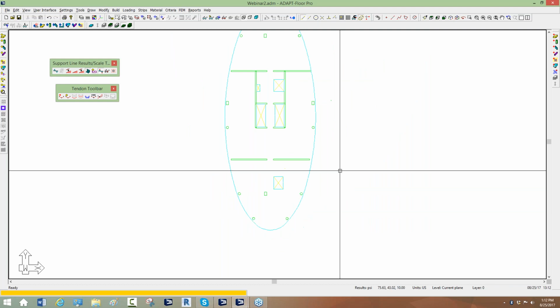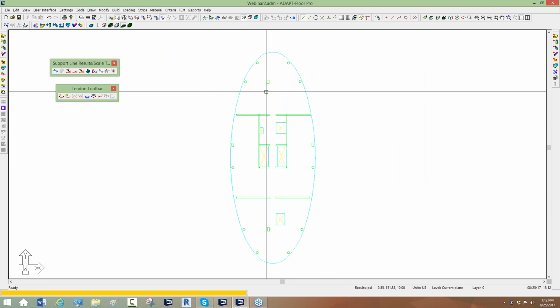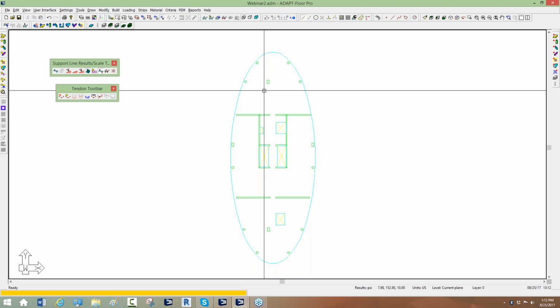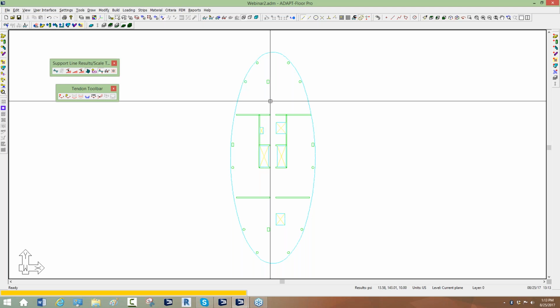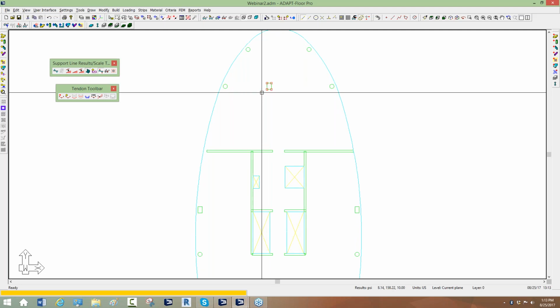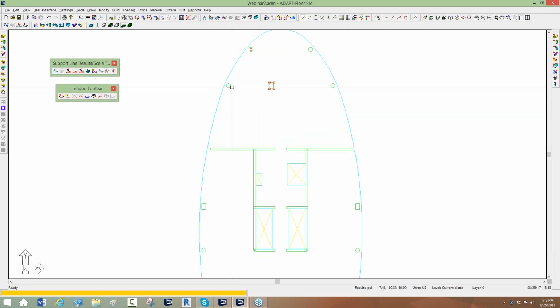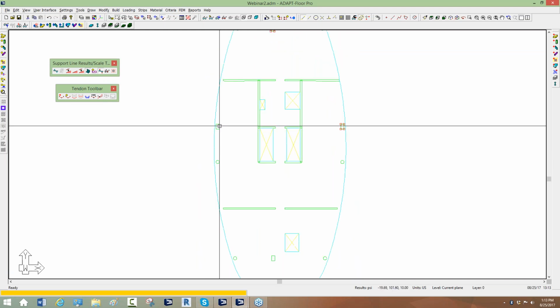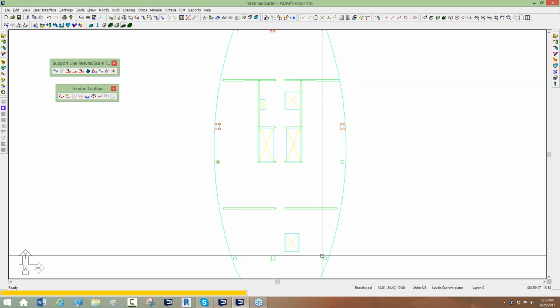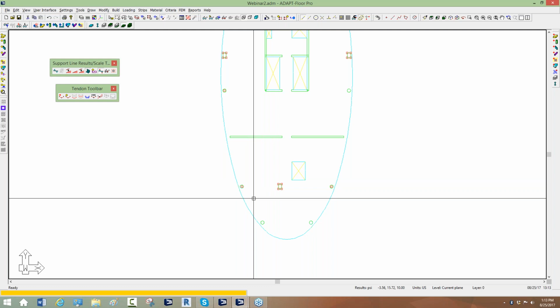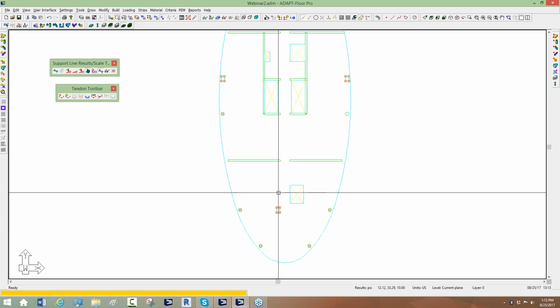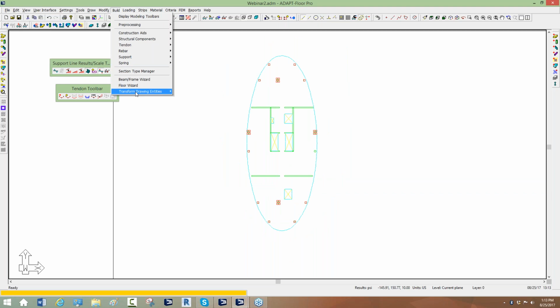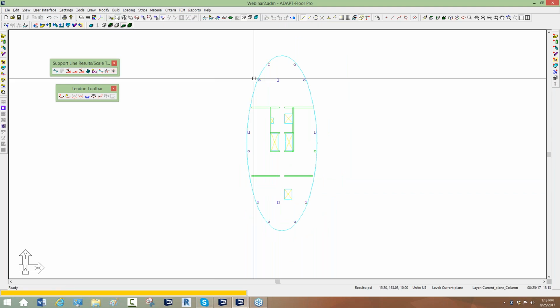So this is now our imported CAD file, and now we have the ability to potentially transform the drawing file into components if we have polygons that allow us to transform. And you can see there are some polygons. Most of the columns here are closed, so we'll go ahead and select these columns, holding Control and snapping on each of these columns, and then I'll use the option for build, transform, and we'll transform that into a column.